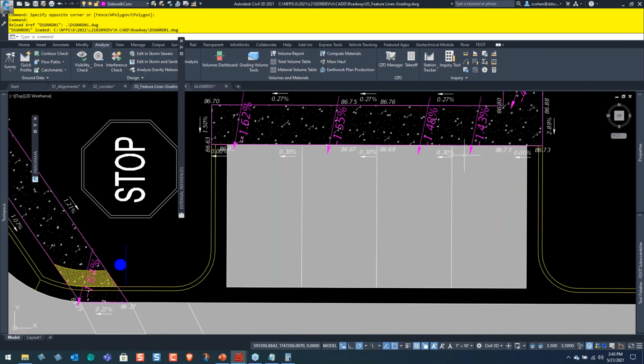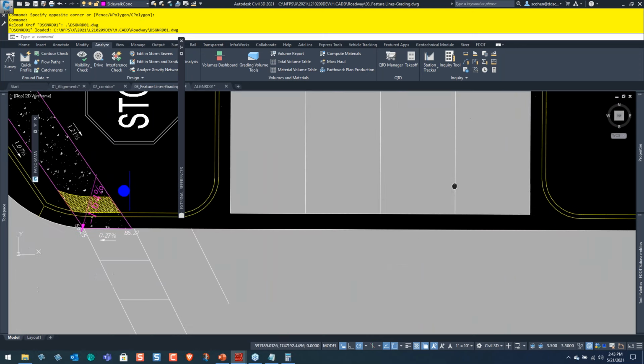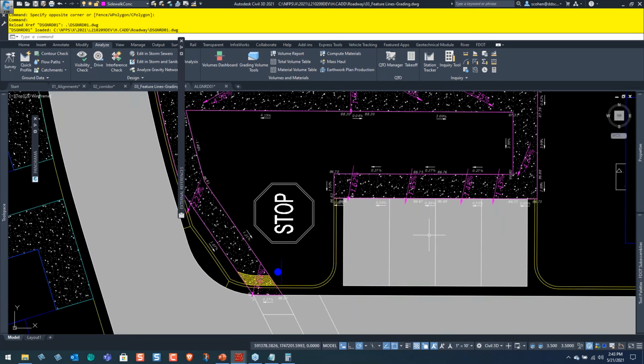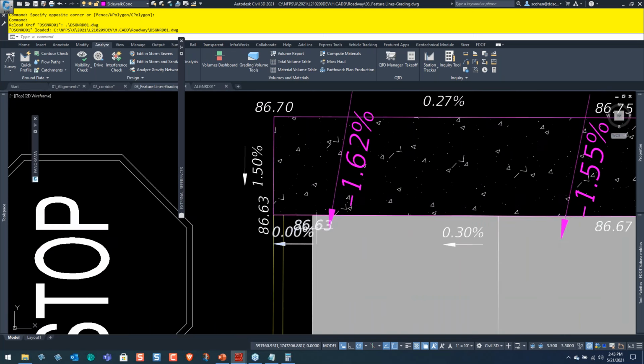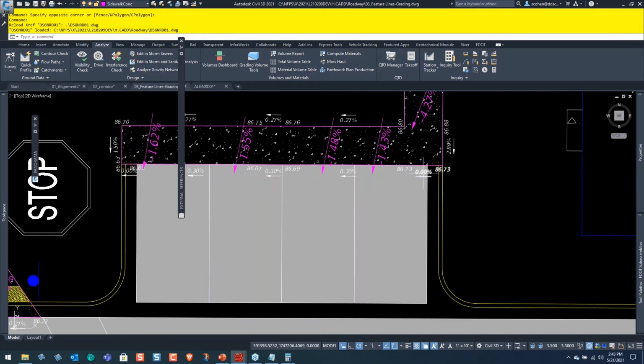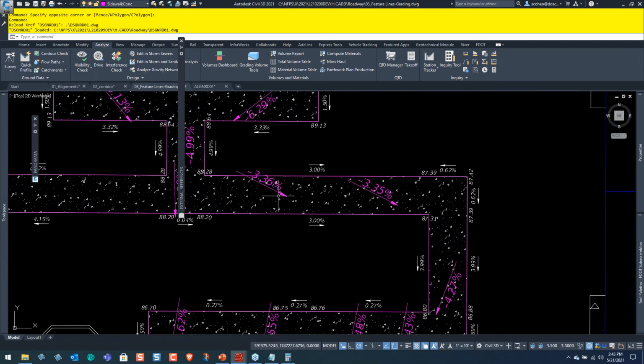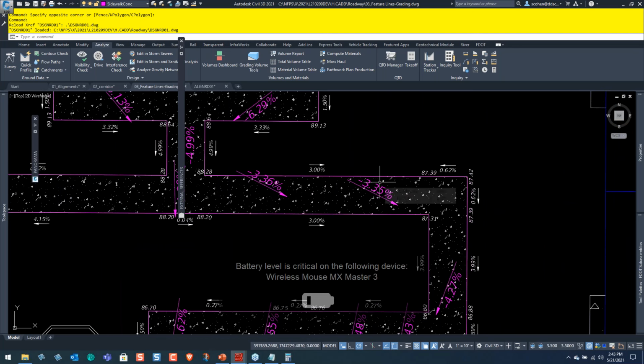That road, I've got a valley. This is going up at 2%. It's going down 2%, up 2%. Actually, where am I here? It's all going down, but that's fine. So this is creating that little area where it's grading down, but the elevation right there is the most important thing. And then from there, I will actually go up at 1.5% or between 2%, of course. And then from there, I also have other constraints like the building over here. So you've got to figure out where you can grade down and grade where it needs to be.